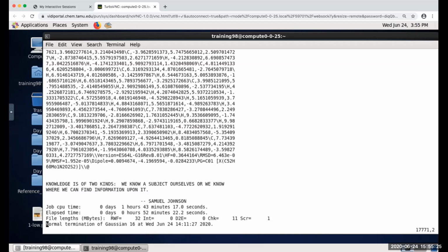If you run it with 2 cores, you'll get a certain wall time. Then if you run it again with 4 cores, you'll get a certain wall time. What you would like to see is the 4 core taking half of the amount of time as the 2 core. Most programs will show you something like elapsed time, job CPU time, or something along those lines, but you can't really gauge based on the job CPU time. My calculation on 2 cores took 52 minutes, which is substantially longer than what we did earlier today. So that's why I say if you got them set up and submitted them, you can just let them keep running, and they should be done when we come back tomorrow.